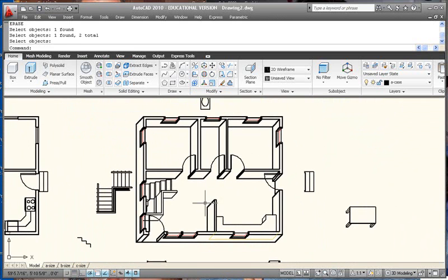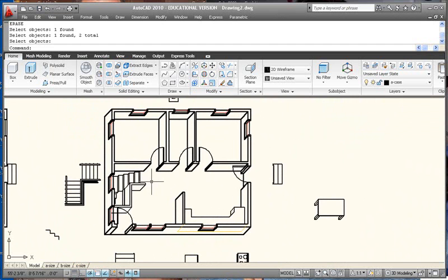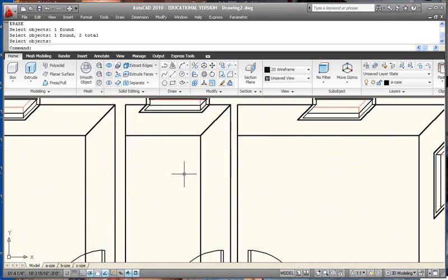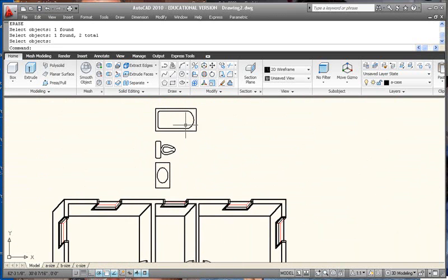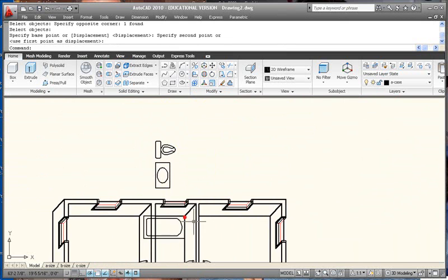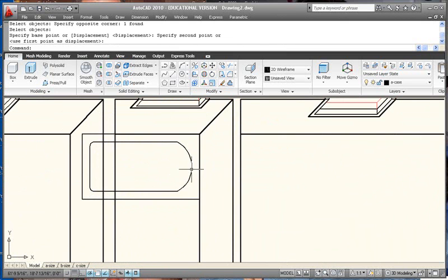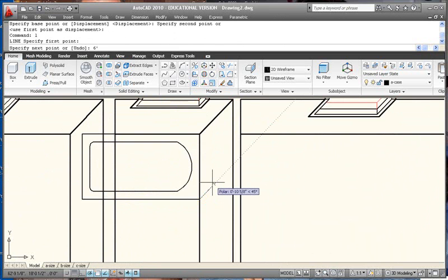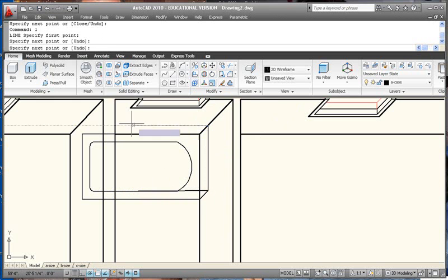All right, so hopefully that gives you an idea of how to move either towards yourself or away from yourself in this floor plan. Let's just do one more. We'll do the bathtub. I'm going to take the existing bathtub symbol that I have and move it from here to here, so it's being represented at the bottom edge or the floor, so that's showing us the floor. Bathtubs are usually only about 12 inches tall, so I'm going to go up from here 6 inches. Whoops. Go across, draw a line across from here, and then across in the back.